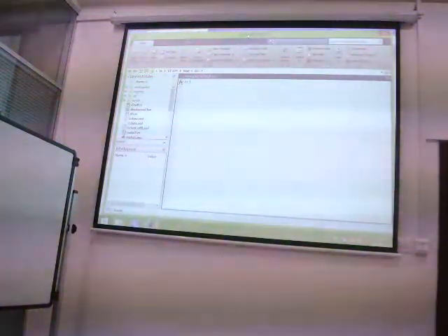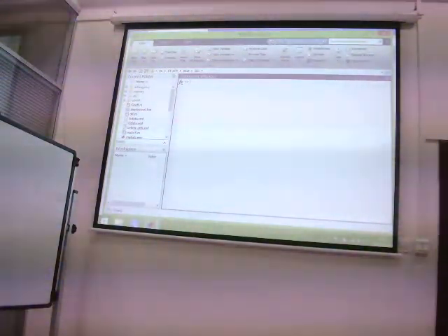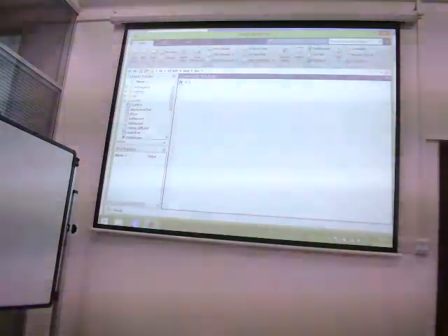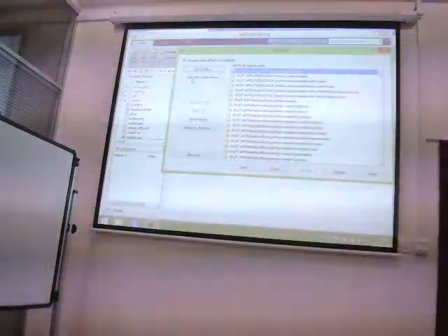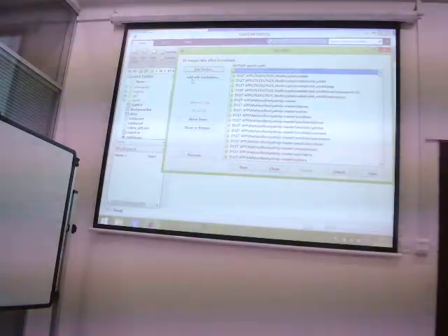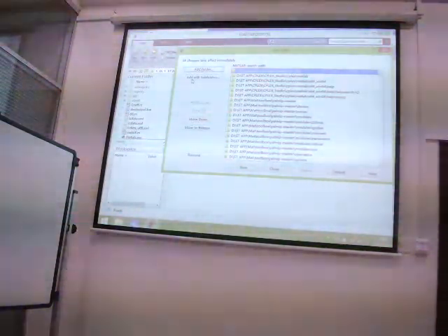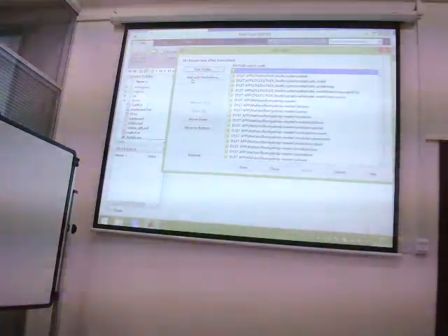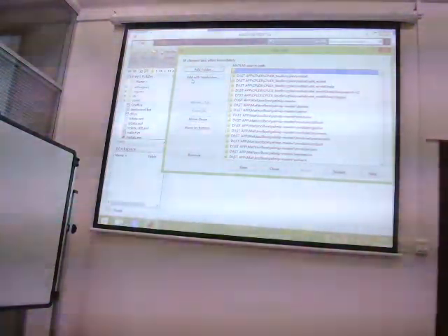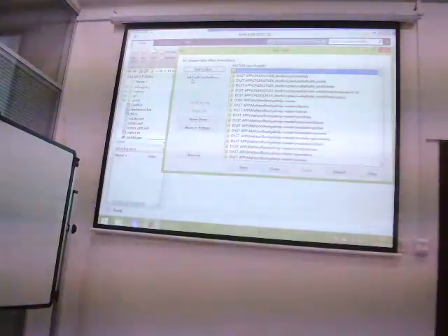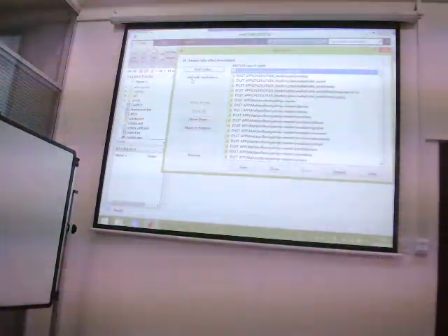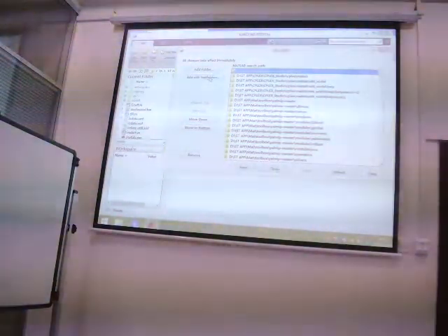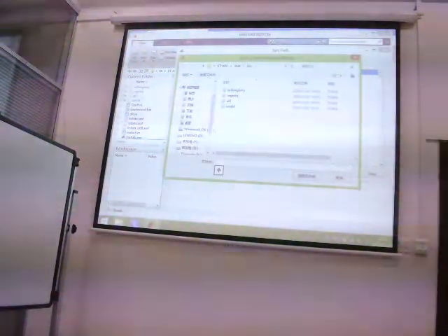Firstly, let's open the MATLAB software. Then click this button, set path. I showed them one day before. Now I show you another time, because this time the MATLAB is in the English version, so it's better for you to understand the languages. I will only show you this time, okay? Remember. Then add MATPower. Add them with subfolders, because MATPower has many subfolders.